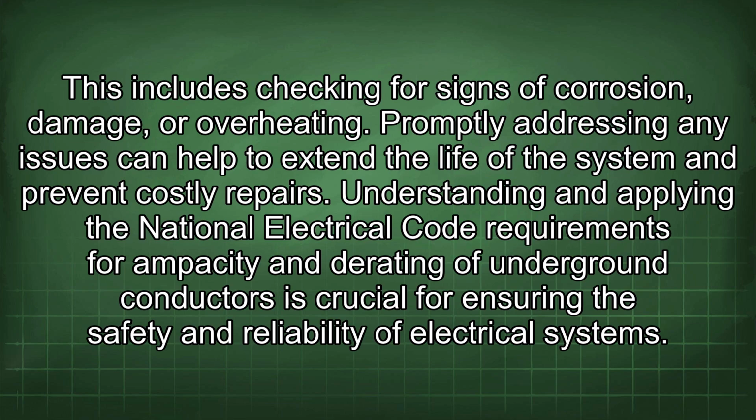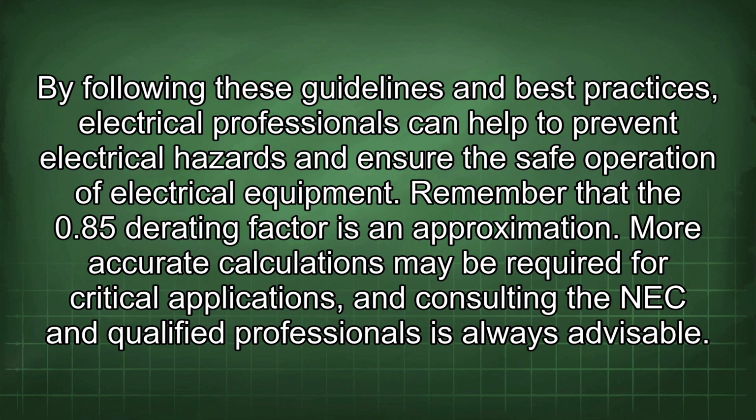Understanding and applying the National Electrical Code requirements for ampacity and derating of underground conductors is crucial for ensuring the safety and reliability of electrical systems. By following these guidelines and best practices, electrical professionals can help to prevent electrical hazards and ensure the safe operation of electrical equipment. Remember that the 0.85 derating factor is an approximation. More accurate calculations may be required for critical applications, and consulting the NEC and qualified professionals is always advisable.